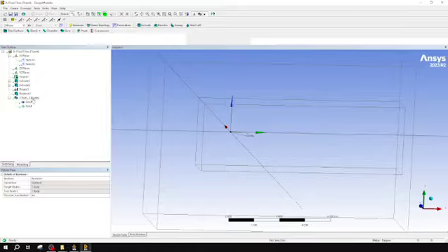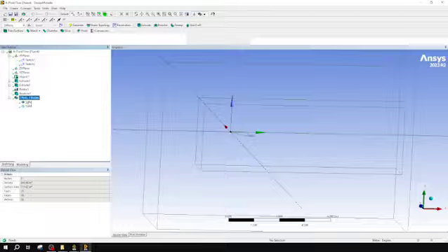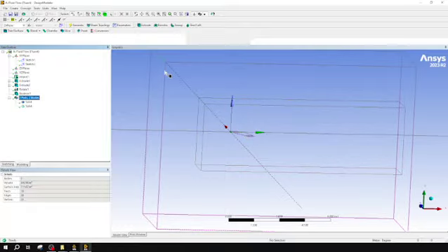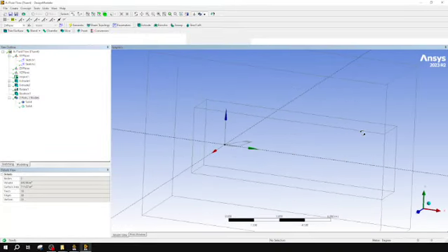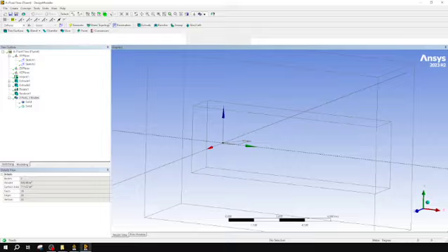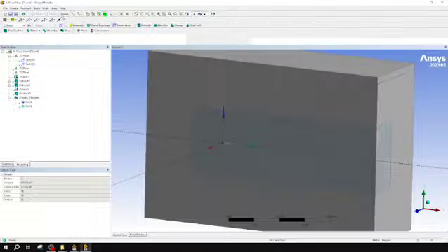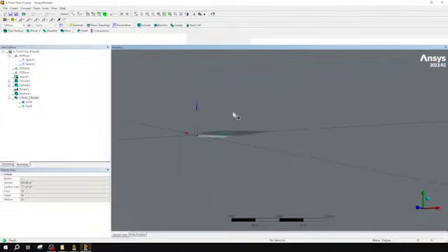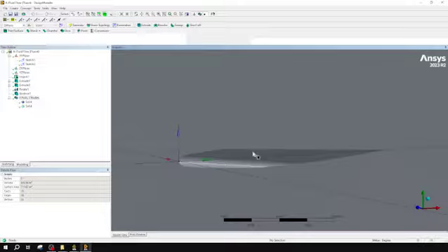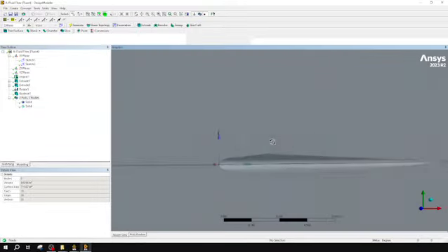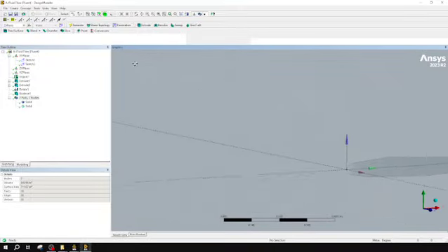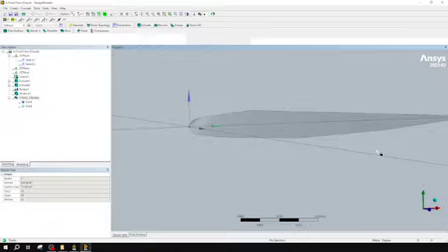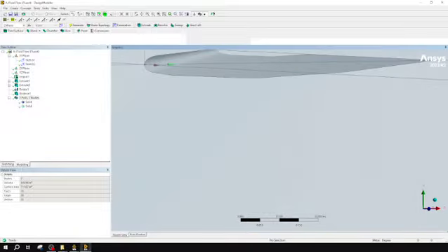you see I've moved down from 3 bodies to only 2 bodies. That's because I've combined my solid large box with my wing. Now, in this wireframe, you might not really see what's going on. So what I'm going to do is I'm going to go back to my view and switch back to my shaded. And what you'll actually see if I go ahead and zoom in is now we have this wing body cut out of my solid body. So it's pretty rough looking in this preview.